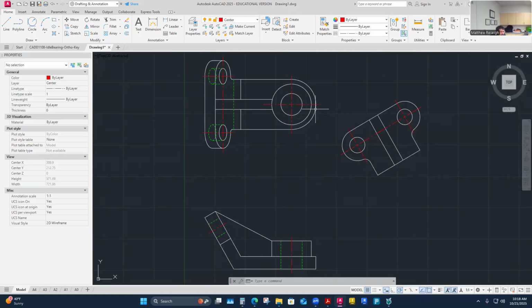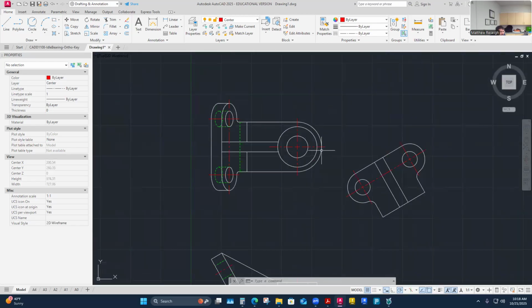So to me, if I analyze this part, I don't love pulling from the extents of the part left to right. I just don't like it. They're strange surfaces and they're edges. So maybe I would think of this as being a great control. Maybe the concentric nature of everything going on here is a great place to start basing dimensions from. If I establish this as a better control on this vertical center line, I could definitely base dimensions from the left and to the right off of it. It's a great control.